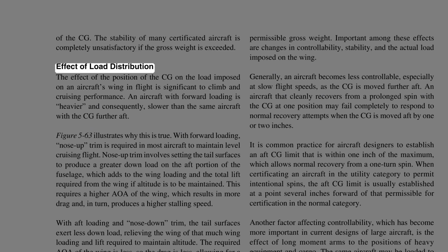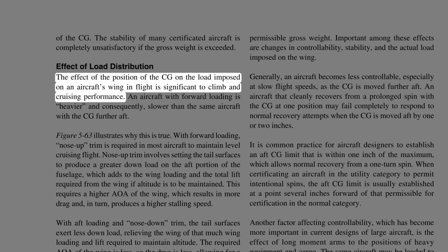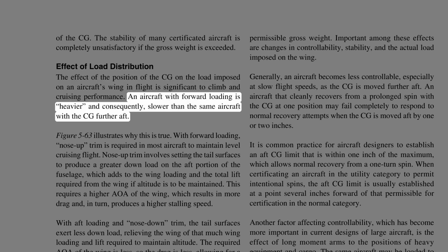Effect of load distribution. The effect of the position of the CG on the load imposed on an aircraft's wing in flight is significant to climb and cruising performance. An aircraft with forward loading is heavier, and consequently, slower than the same aircraft with the CG further aft.